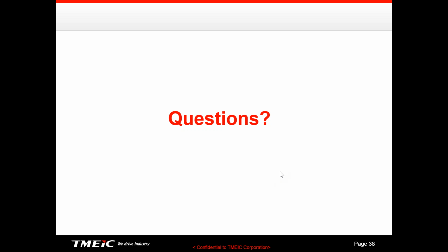The next question, Pablo, your question about using step-down transformers between the VFD and the motor. The issue there is you need to make sure that the transformer is rated with a K factor to handle that application. So you need to work with the transformer manufacturer to make sure he sizes it properly.